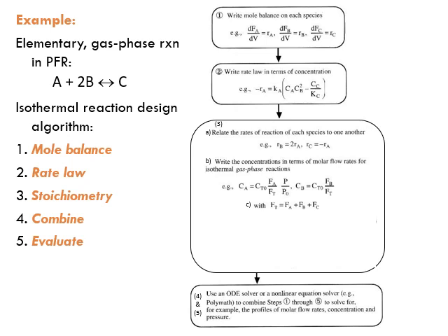Are you going to use Ci? No, you're not going to use concentration, because concentration is a bad indicator to measure the progress of a reaction in a gas phase system, because the volumetric flow rate could change for reasons other than reaction. So I'm not going to use Ci. Are you going to use Ni? No, it's a plug flow reactor, a continuous flow system, so I'm not going to use number of moles. I'm going to use the molar flow rate, Fi.